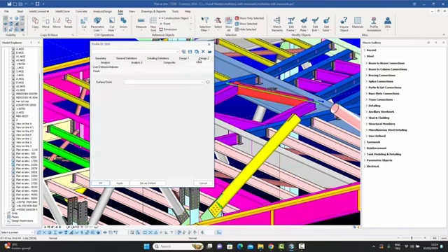And when I go inside the UDA tab, I see that right now there's only one caption called finish. We could have multiple options depending on how many group types we have defined. In this one, we have only defined one caption, which is finish. And under that caption, we have defined only one variable called surface finish. We could have multiple variables under the finish caption. We could have 10 different variables in whatever order that we wanted them to be. And inside surface finish, we've given it the option of either normal paint or fire resistant paint.